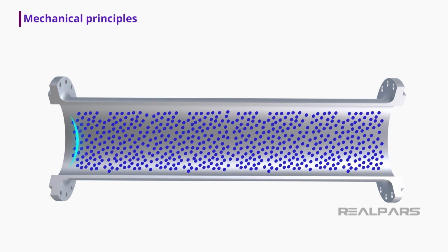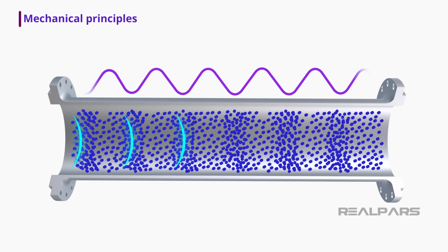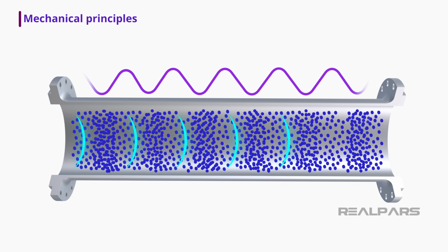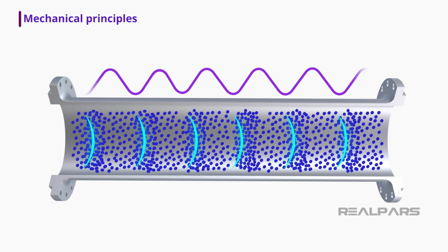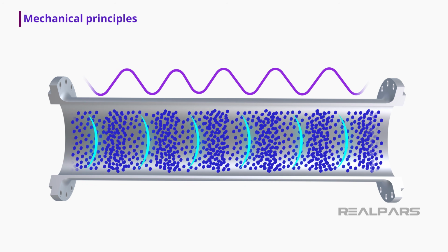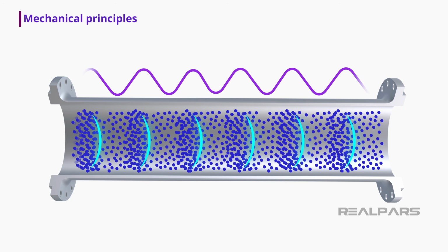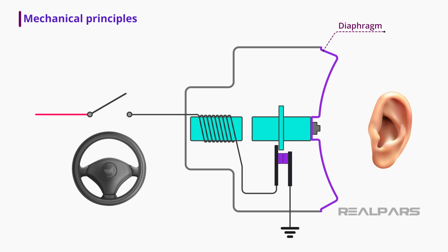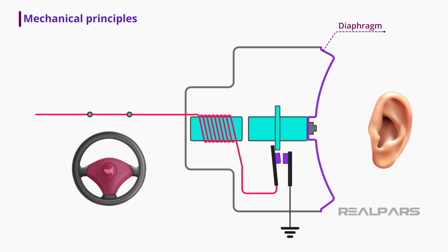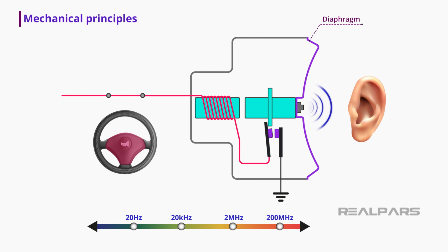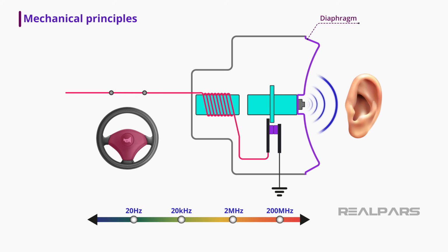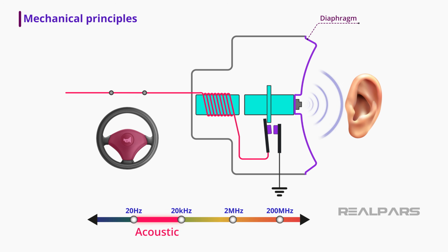Sound waves move through a fluid based on the transmission of vibrations through the fluid. These mechanical oscillations between molecules of the flowing fluid are passed to adjacent molecules, thereby transferring the wave to those adjacent molecules. A car horn is heard because a rapidly vibrating diaphragm transmits high-frequency waves through the air, the fluid of transmission in this case. We are able to hear the sound because the vibration frequency is in the audible range, about 20 Hz to 20,000 Hz.